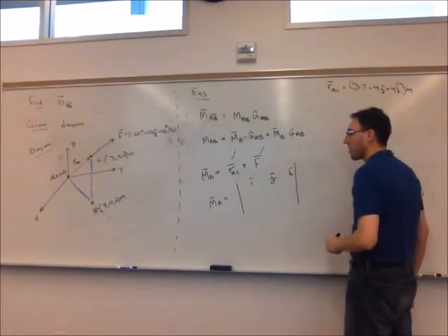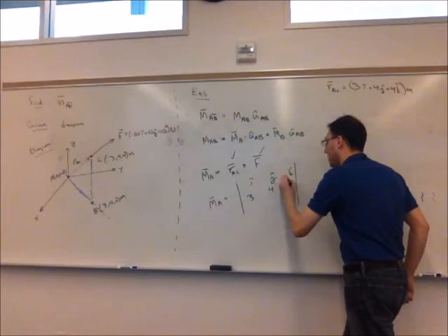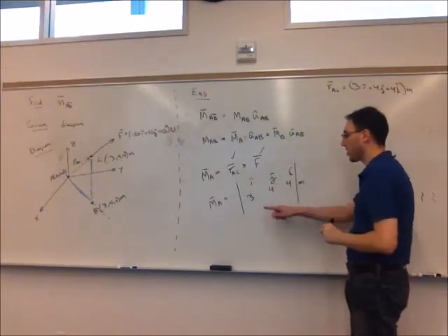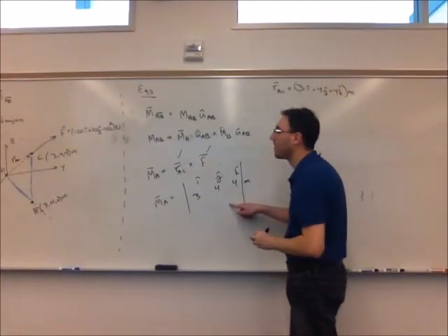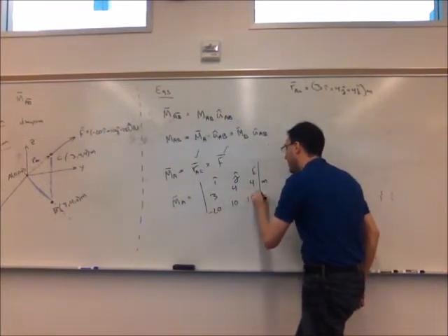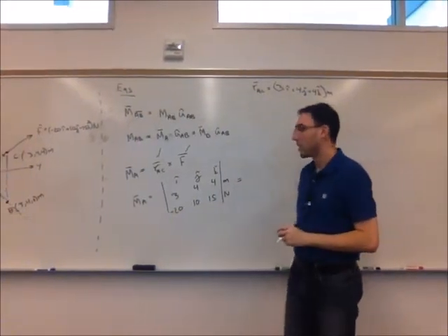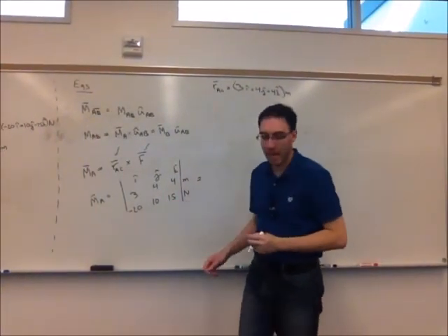Going through this cross product step, second line, r_AC: 3, 4, 4. And then the third row, the components of F. We're given negative 20, 10, and 15 newtons. As before, I'll leave it to you to expand this out.